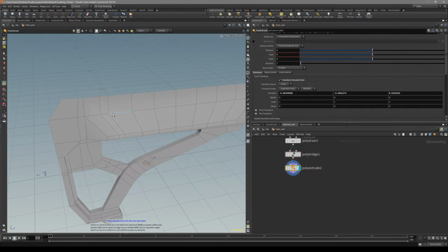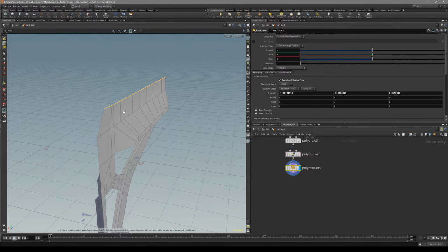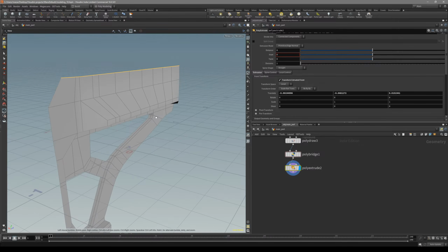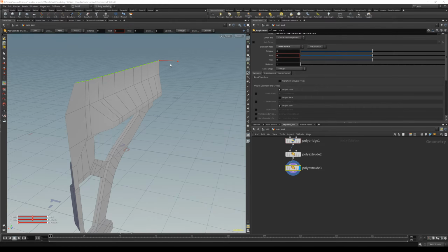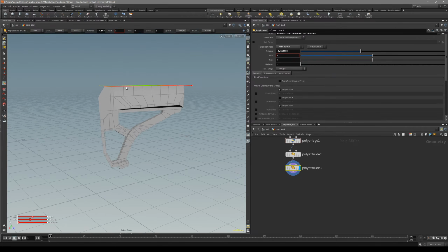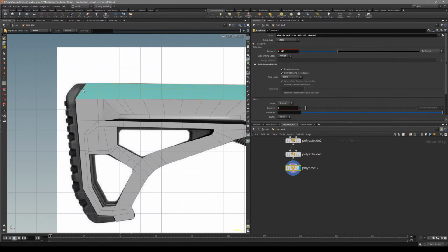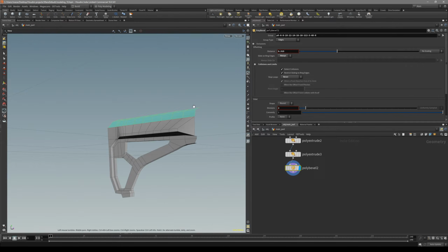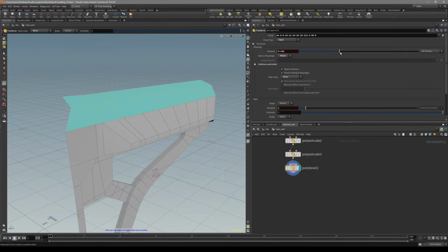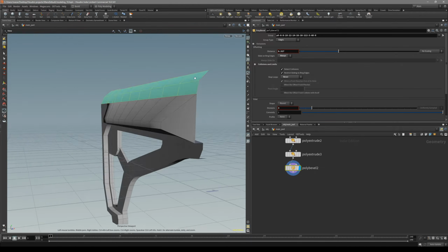So first of all, let's select it and we can probably extrude it. Let's extrude it like that, and then what we can do is bevel it. So why are we doing it like that? Since we want to probably take care of this also right now, that we can extrude it, and also the back of it, since we want to boolean, let's just take care of it right now. The thing is that we're not really sure what the curve for it is.